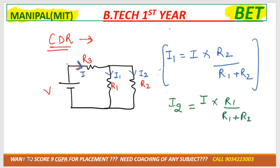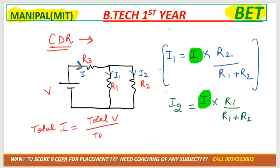Now the question arises, ma'am, how can we calculate I, right? Maybe if they give you the current source, then you'll get I directly. If they don't give you the current source, then you need to calculate I. So I is the total current. What will be the formula for total current? Total current is equal to total voltage divided by total impedance. Total voltage is given. Total impedance, or total resistance, is how much? R1 is in parallel with R2, and R3 is in series.